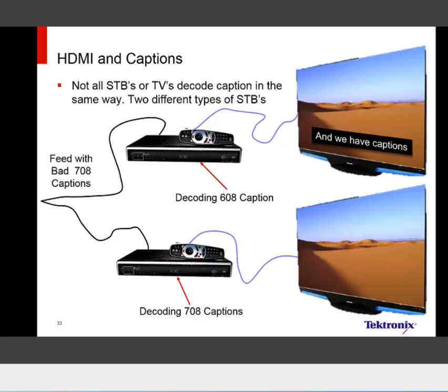When you get into this situation, you'll have multiple types of indications coming back where not everybody is having an issue, but X% of boxes or X% of customers are complaining about bad caption issues. You have to try to duplicate these conditions to the fullest extent possible, even down to the model of set-top box within the same manufacturer, because some of them do it differently.